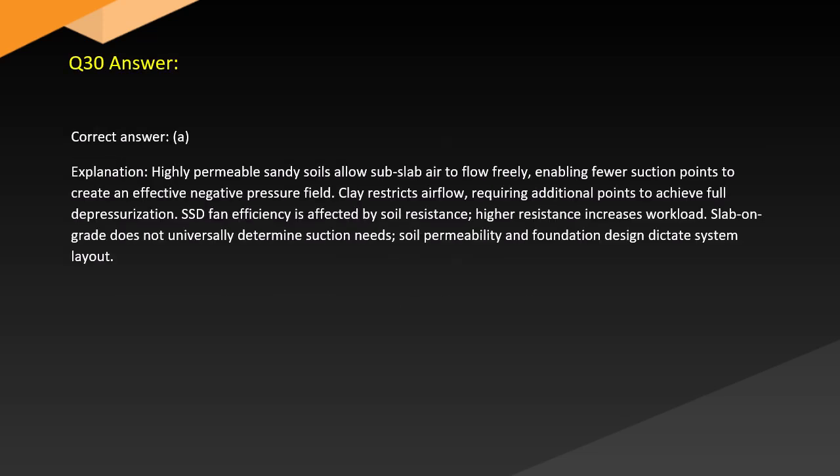Answer. Correct answer: A. Explanation. Highly permeable sandy soils allow subslab air to flow freely, enabling fewer suction points to create an effective negative pressure field. Clay restricts airflow, requiring additional points to achieve full depressurization. SSD fan efficiency is affected by soil resistance. A high resistance increases workload. Slab-on-grade does not universally determine suction needs. Soil permeability and foundation design dictate system layout.